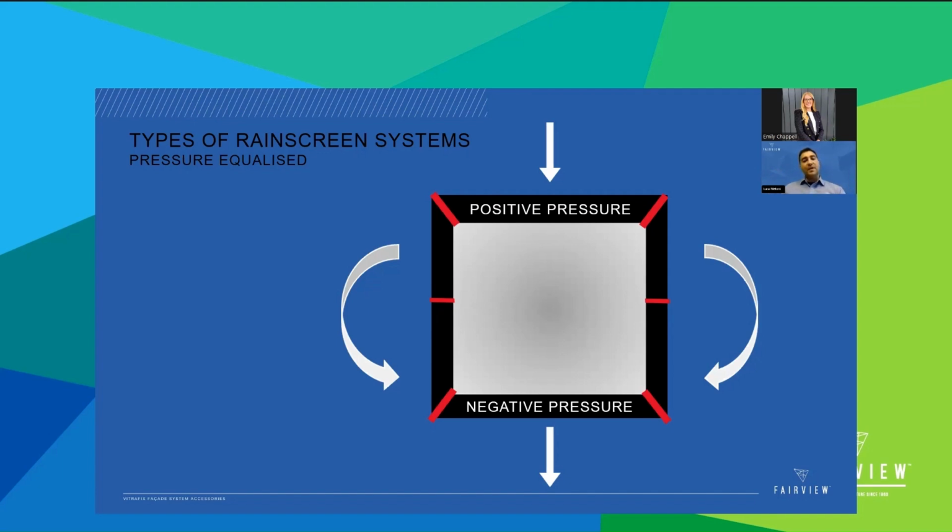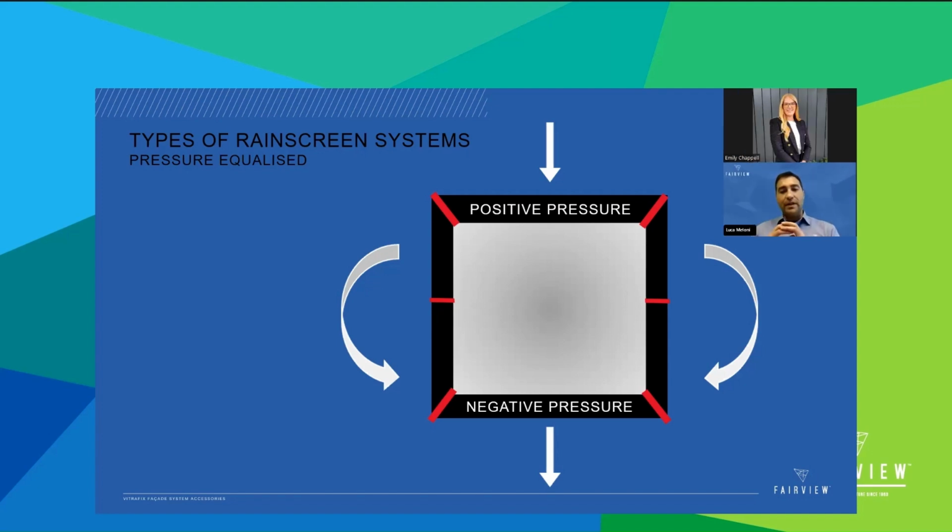In this system, the top of the rainscreen cavity is not vented. Vertical cavities are intentionally sealed to allow the chambers to fill with air when exposed to high winds. As the wind fills these chambers, the air pressure inside equalizes with the outside pressures, preventing the water from being drawn up through the cavity.